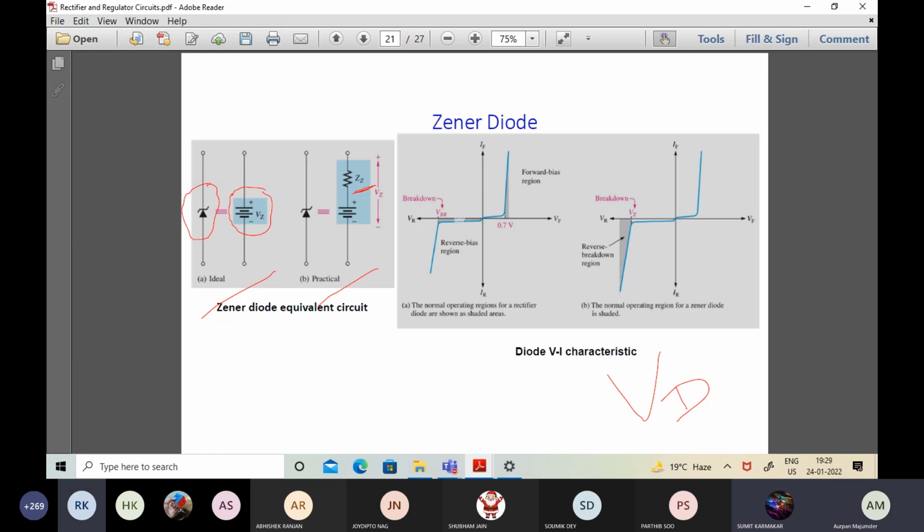You all have studied the resistance of a diode, the incremental resistance, the dynamic resistance of a diode. I'm talking about that scenario only. But the point is, the factor ZZ or RZ, whatever we say, that incremental resistance of the Zener diode, is effective under reverse bias. So here we are talking about the incremental resistance of the diode in the reverse bias state. If we consider that information along with the corresponding voltage source as shown there, then this combined representation is represented as Vz. More to talk about it from the other slide, which I'm going to present.